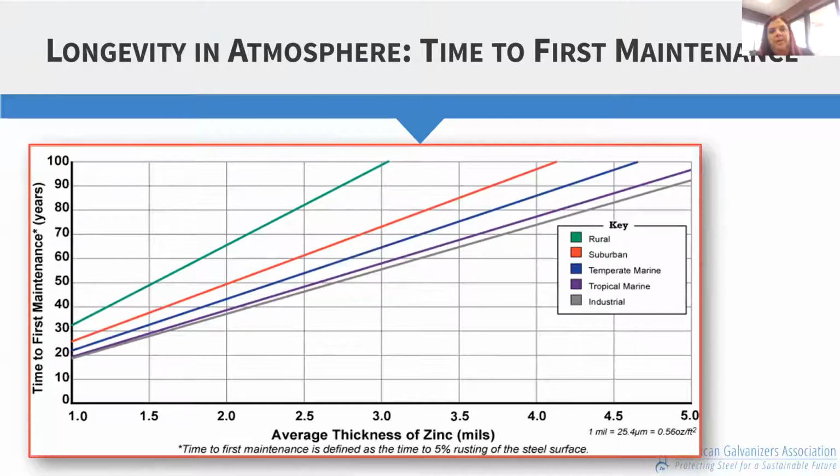So as I mentioned at the beginning, a lot of the reason to use hot dip galvanizing is for its longevity. And even in a temporary structure, this could become important because sometimes our best laid plans don't work out how we expect. Maybe we thought the bridge was just going in for 5 years, but it could end up being there for 20 or 30 years, depending on the situation. So one of the advantages of using hot dip galvanized steel is that basically you pay for it up front, you put it up, and you can more or less forget about it. So if it's in a remote area that's difficult to access or anything like that, you really don't have to worry too much about maintenance or closing it down.